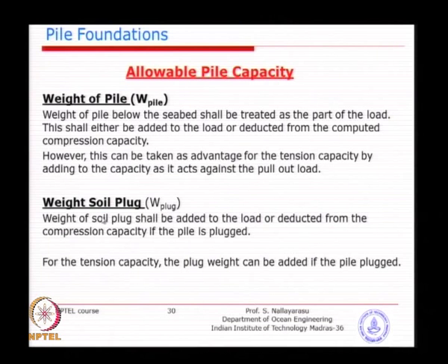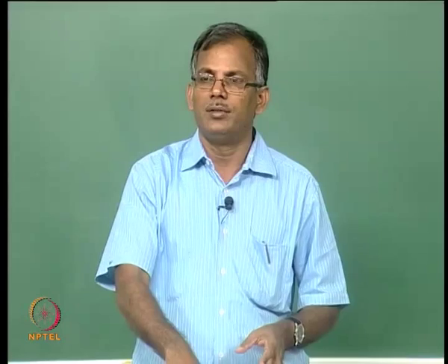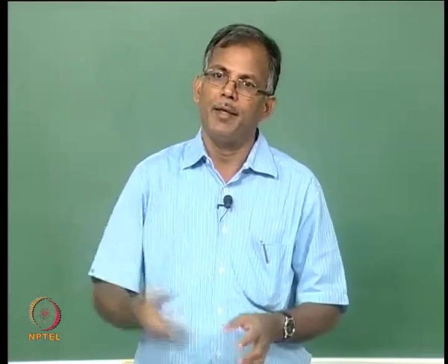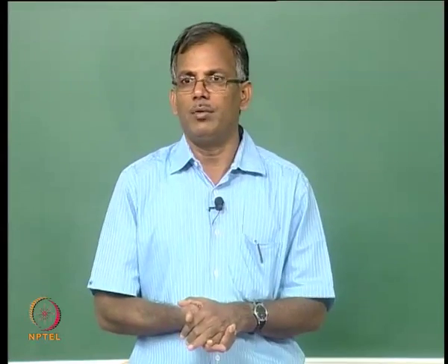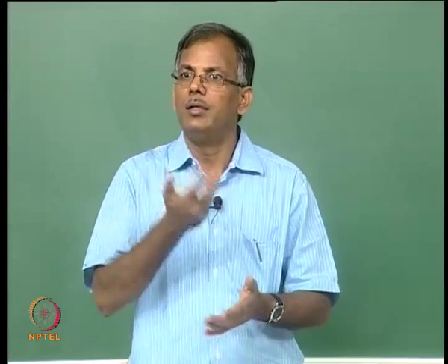Now, how do we find out allowable capacity is just a simple matter of taking the ultimate capacity divided by the factor of safety, but then the added information that we need to remember is the weight of the pile and the weight of the soil plug. Remember, we were talking about when you drive the pile inside and just pull out the pile, if the pile is plugged, what will happen? The soil will come out together with the pile itself.